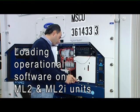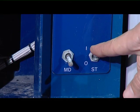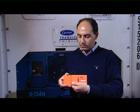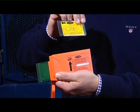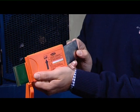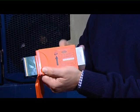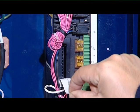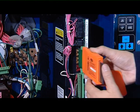Loading operational software on Microlink 2 and 2i units. Switch off the unit. Insert the PCMCIA card inside the adapter as shown. Remove the white label from the programming slot and insert the adapter.